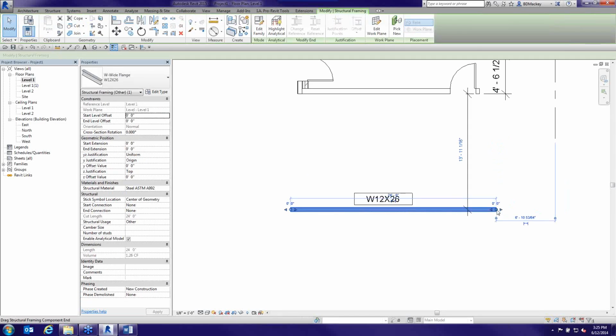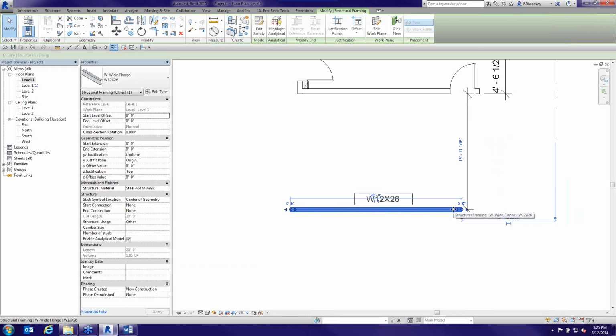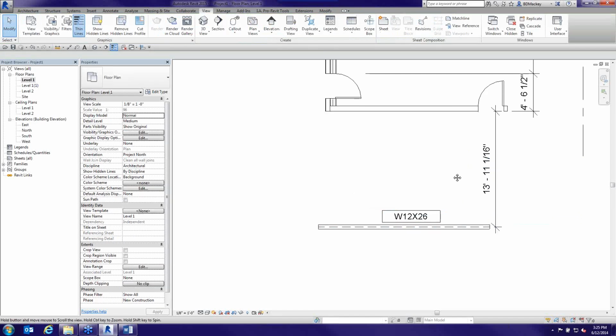If I just take this object, drag, type in 20, boom, it's 20 feet long. So dragging it from the end you want works with any line-based object: walls, ductwork, detail components that are line-based. Great tip. Just drag it where you want and start typing. So I think that's kind of getting into the same thing when we get there.